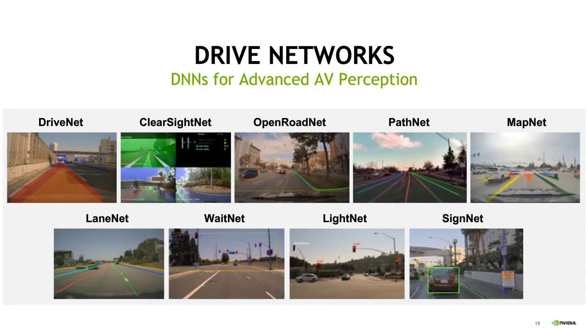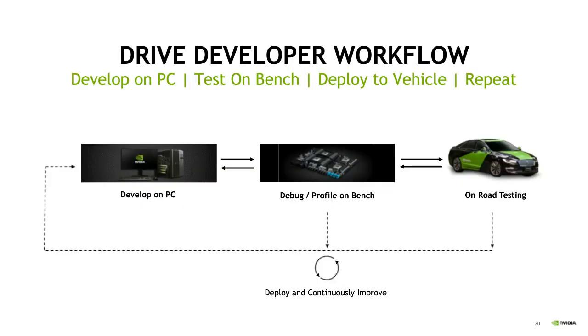Before we go too far, I'd like to walk you through our recommended workflow for Drive software development. All work begins on your host development environment, which is an x86 PC running Ubuntu. When you're ready to test on the Drive embedded platform, we provide the capabilities to cross-compile your software for the target. We also provide tools for debugging and profiling to improve performance on the Drive platform.